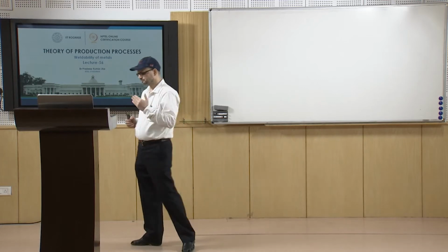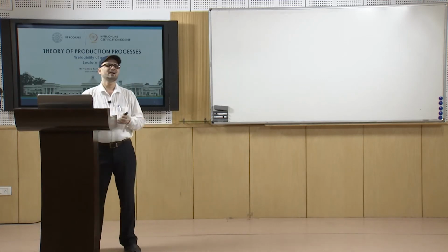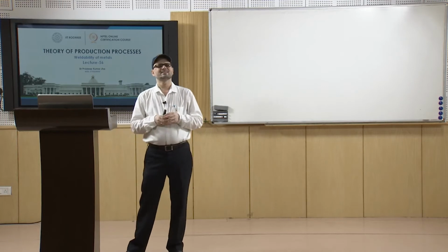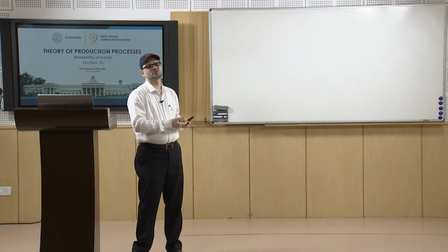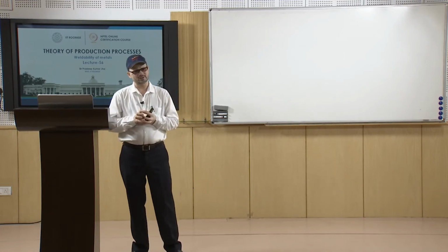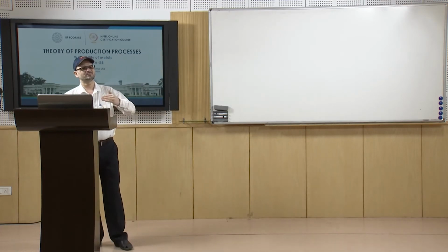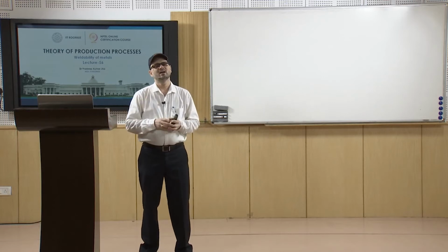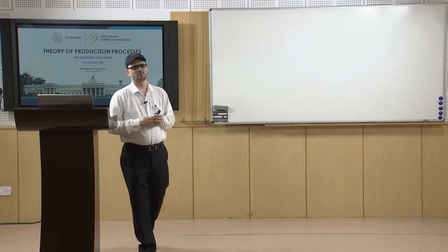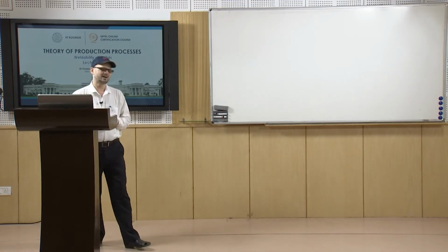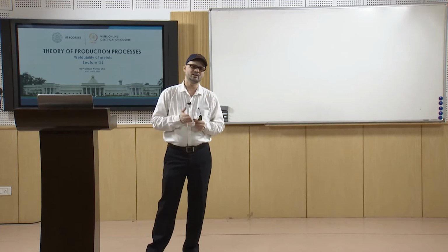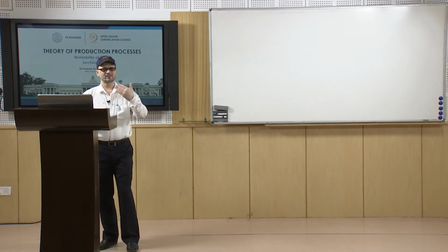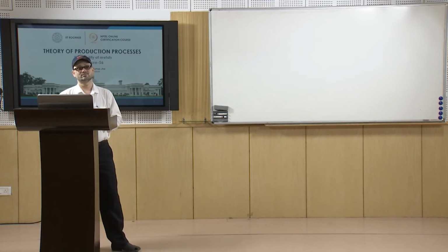So, a weld must be mechanically sound. Then only you can say, in most of the cases, if it is mechanically sound, then at least you can ensure that there will not be premature failure of that joint. Otherwise, if you have the formation of voids, if you do not control the porosities in the weld zone, or if you are not able to see that you have different kinds of weld profile, or you have cuts or cracks, in that case it will not be a sound weld, and then it will reflect on the mechanical properties of the welded joint.